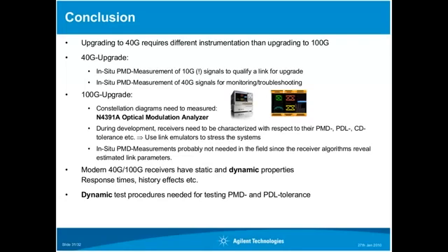We think that people probably would need link emulators for showing that their receivers are tolerant to PMD, PDL, CD, whatever. At this moment, I think people are on the stage of using measured data and simulating using real measurement results, but simulating the effect of their receiver algorithms, because there are not too many people around having an FPGA or an ASIC available for doing this. But I'm sure very soon we will see this.